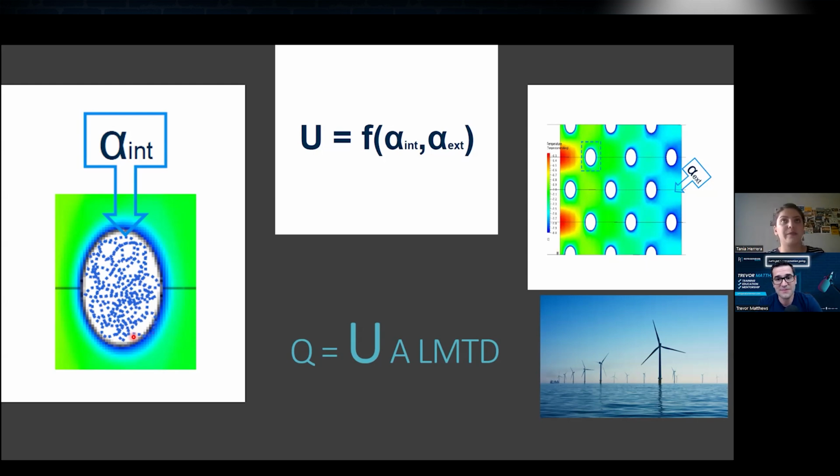Yes. So, well, I will show you a picture later that will also describe this better. That we want the liquid to surround all the wall of the piping. I love that. So that's on the internal heat transfer, and now we have the external heat transfer. This one refers to the heat conductivity of the materials as well, because in this case, the fins are where almost 90% of the heat transfer occurs.